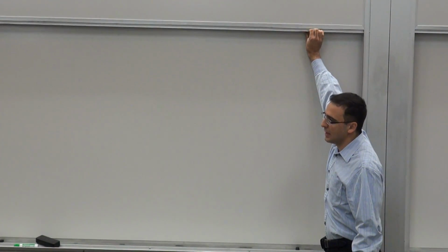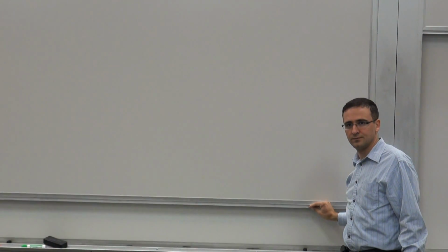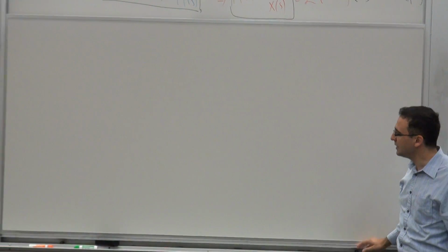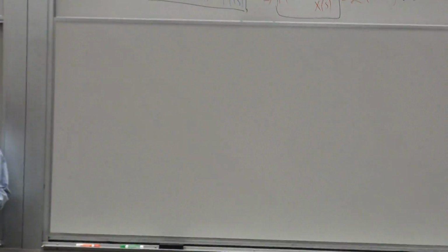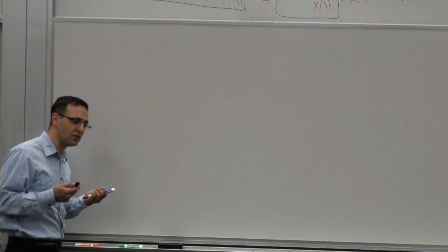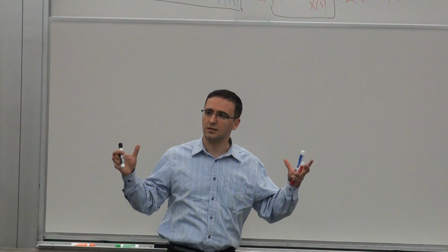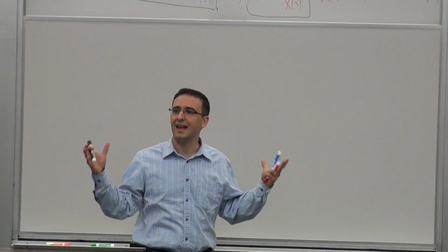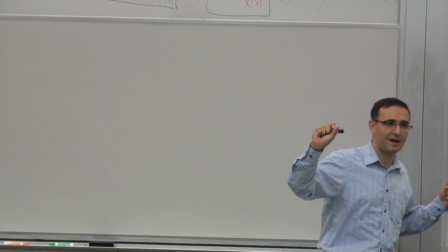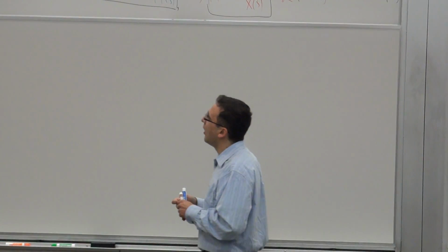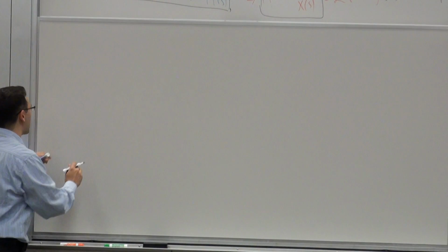So now, if you have a transfer function, you can define a transfer function. Now, what can we say about the transfer function itself? You can show that the transfer function of a circuit consisting of lumped elements, namely elements that are like two terminals, much smaller than the wavelength as we defined them before, can always be written in a fractional form.